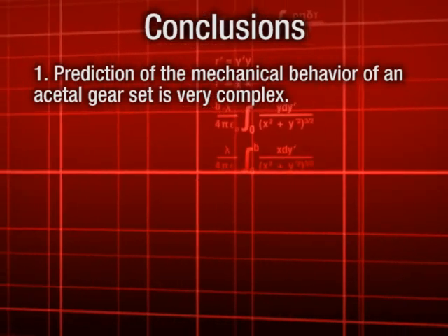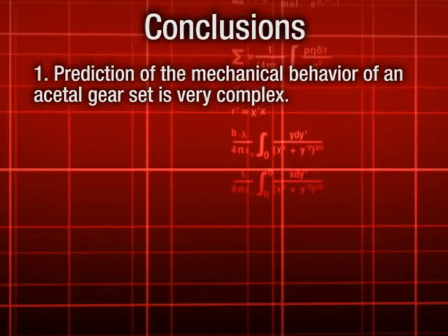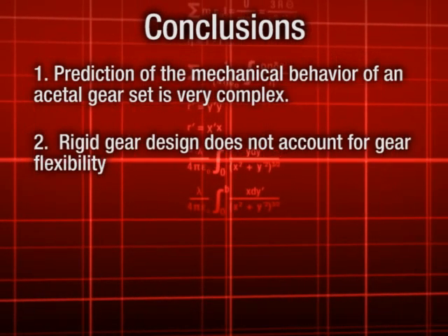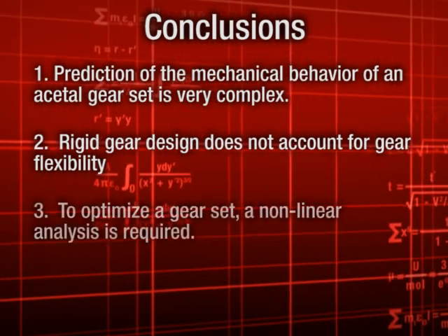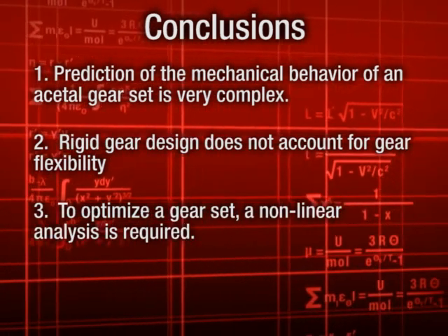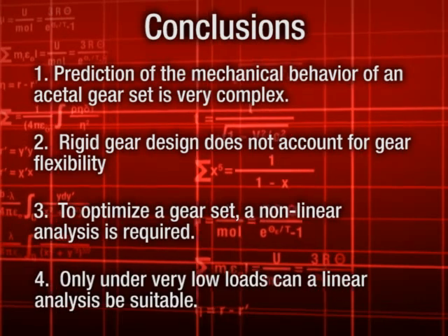In conclusion, the prediction of the gear pair is very complex. The rigid design does not account for the gear flexibility. To optimize the gear set, a nonlinear analysis is required, and only under very low loads can a linear analysis be suitable.